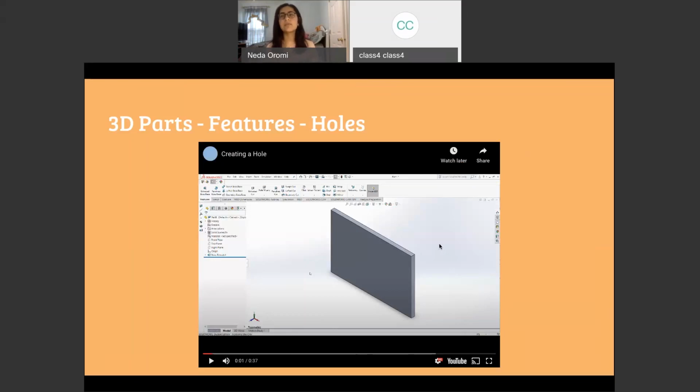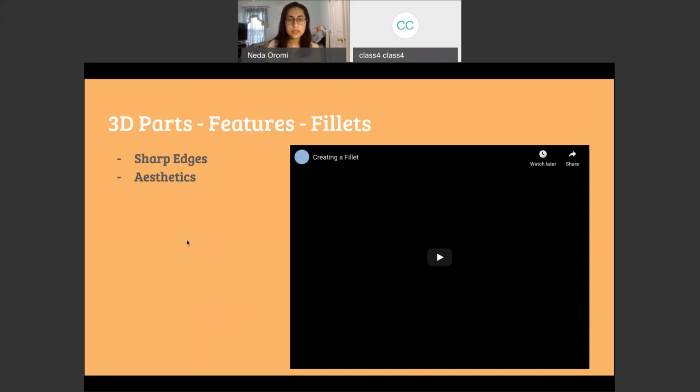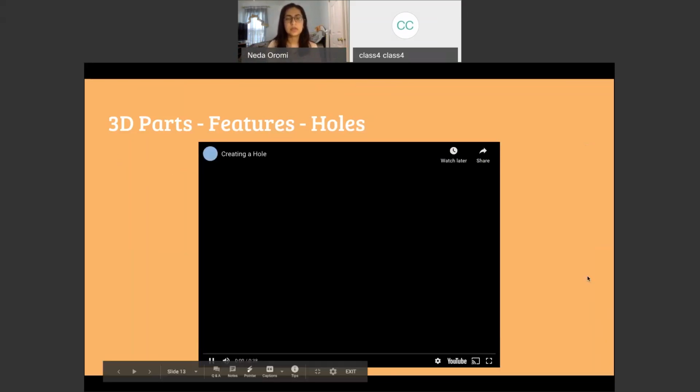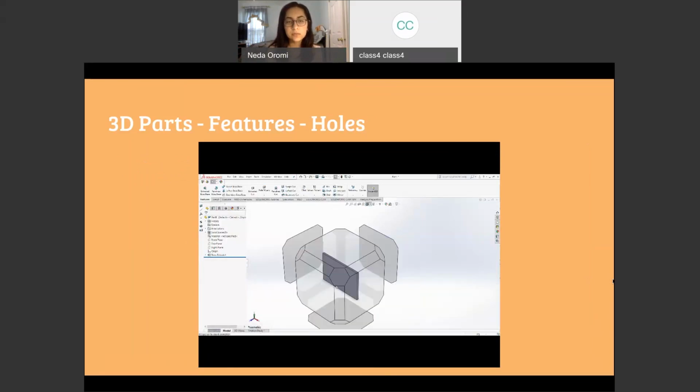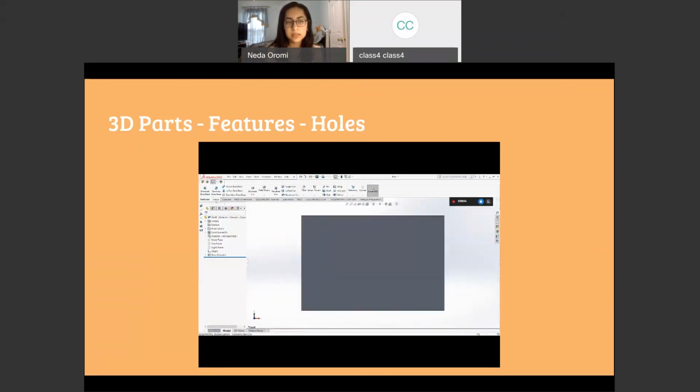But if you have your hole sketch and your boss space sketch different, that'll help with making sure that things don't extremely change if you want to change a dimension to it. But oops, this is a little video on how to create a simple hole. So I'm going to orient it to the front and then go to sketch and start a sketch on top, select a hole and make a hole, and then I need to dimension it.